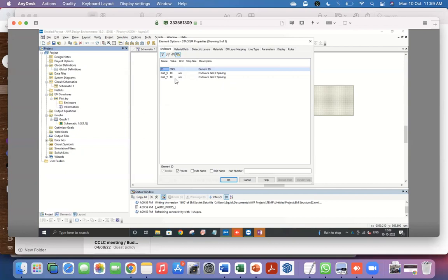But now, if you think about this microstrip, which is 1,000 microns wide, and I have a 10 micron grid spacing, that's already a lot. Right? So if you are too fine, the system actually will recognize that, and this process is called meshing. You'll see the mesh in just a second. It breaks up the system into these polygons, and then those are where the Maxwell's equations are solved. So you don't have resolution within the polygon, it's just the boundary condition. Things, electric fields and magnetic fields will change from one polygon to another polygon. And there will be a boundary condition applied to the simulation. So for now, we will leave it at 10 micron by 10 micron.